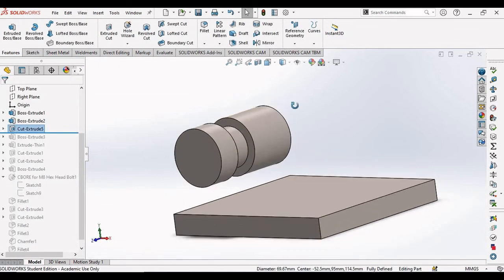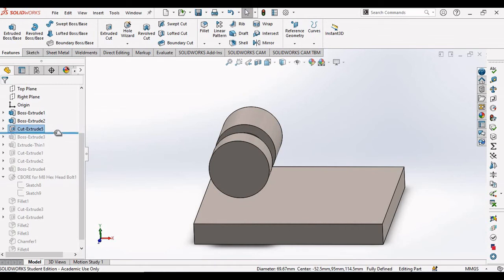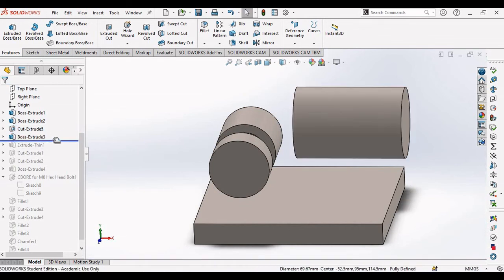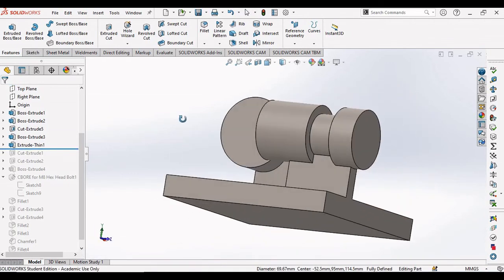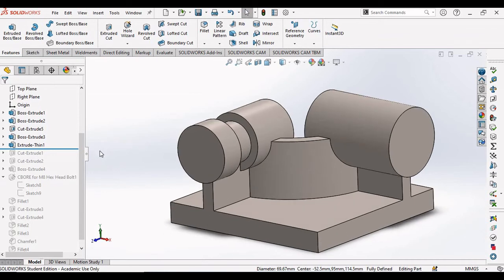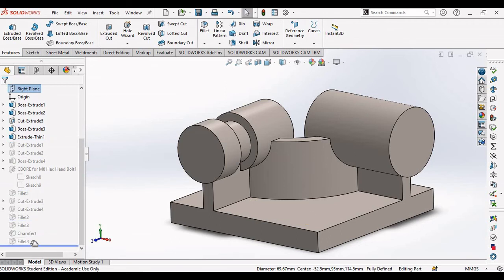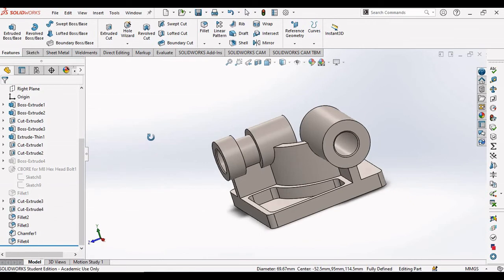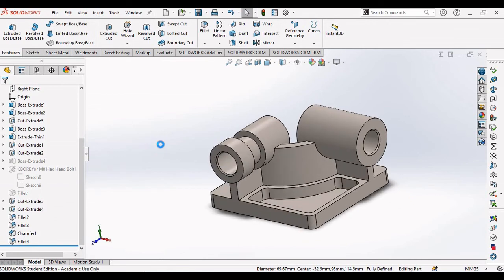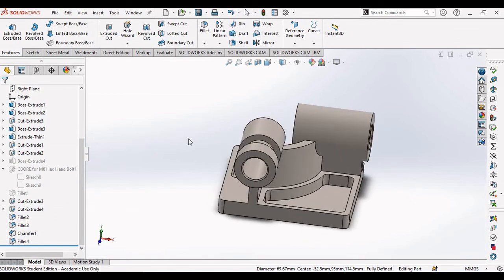Okay, we have got this slot made, and now when you bring it down, and this 10, see, everything is taken care of, right? So that's a very important thing. You have to always use this particular hand icon to drag to a particular location of your sketch where you need the modification to be done. Now Control S. So I guess we have completed.